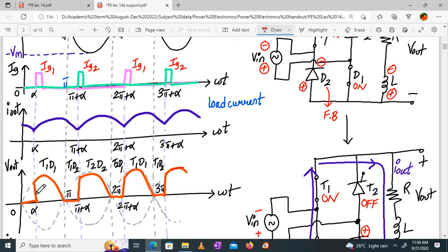So have you drawn the waveforms? One good thing about semi-converter is that the output wave shape in case of continuous current is same for R load, RL load and RLE load. Output same है ना, and the expressions are same. Only in case of discontinuous it changes. So draw whatever you want to draw quickly. Waveforms are completed.